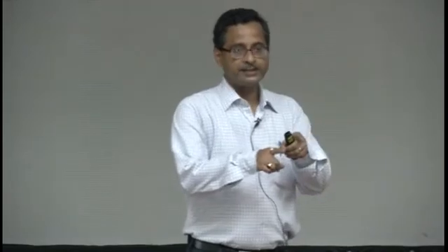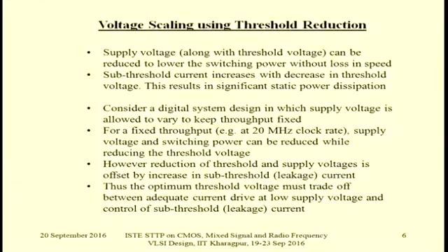Basically, the total power has different components. For static power, nowadays the design is made in such a way that a direct path from the VDD rail to the ground rail may not be there. We always make use of CMOS circuits, but sometimes, for the input-output buffer, BiCMOS circuits are used.